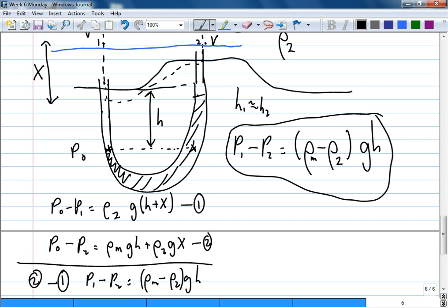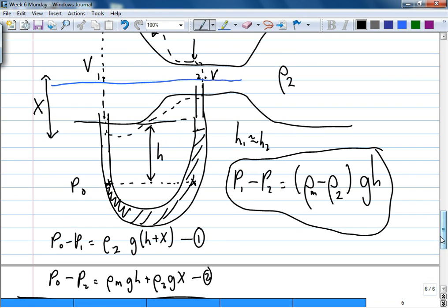So, I put a pitot-static tube, I measure the pressure, but in your experiment, you used a pitot-static tube, though it could also be done using a pressure gauge, pressure transducer, and other types of equipment to measure pressure. But in your case, you did it using a manometer. Now comes the interesting part. We measure the pressure, so P1 minus P2 we know. We want to work out what the velocity and the flow rate is. That's the whole point of putting this device there, not just to measure pressure. Measuring pressure is a means to get to the end, which is the flow rate.